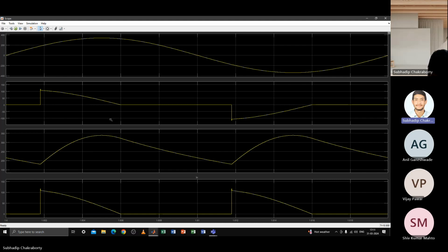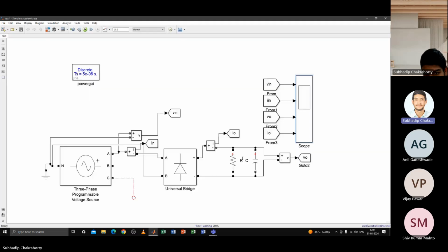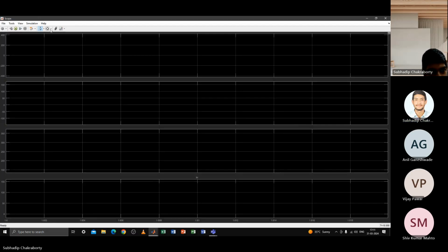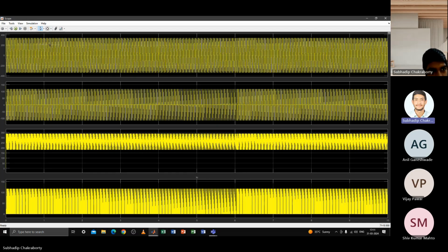When the diodes are forward biased, you can see the charging of the capacitor, that is, the output voltage rises. During that time the time constant is different. During the discharge path, only the RC circuit is involved because no diode is conducting at that time, so it is longer due to the larger value of resistance. R is more, right? We considered that at the beginning. So that's why what is happening is this waveform, again I am zooming.